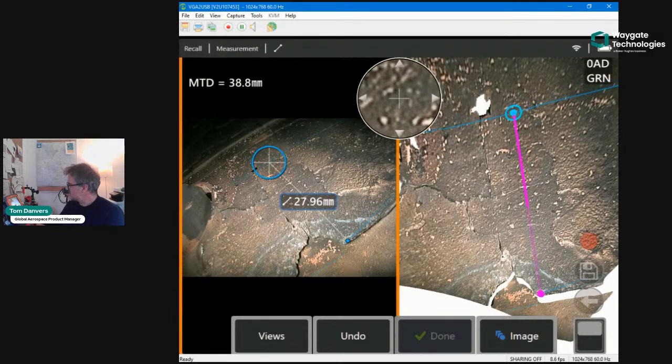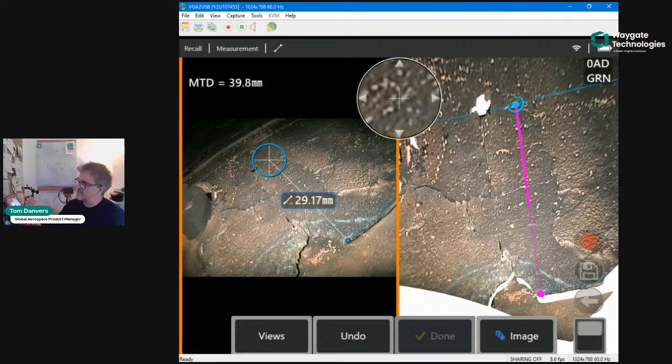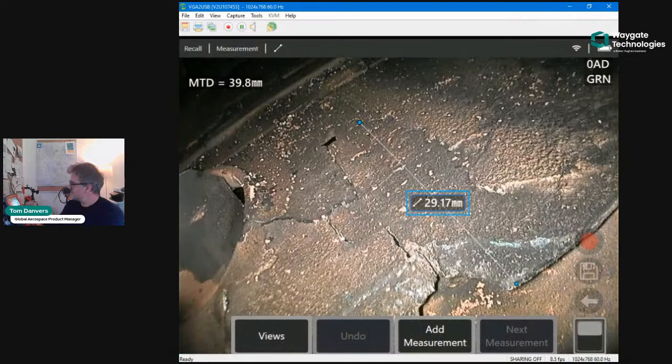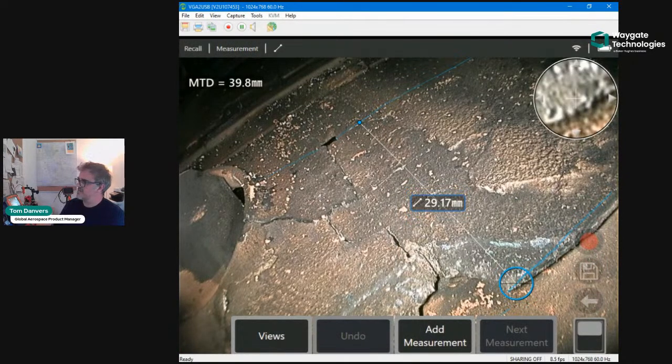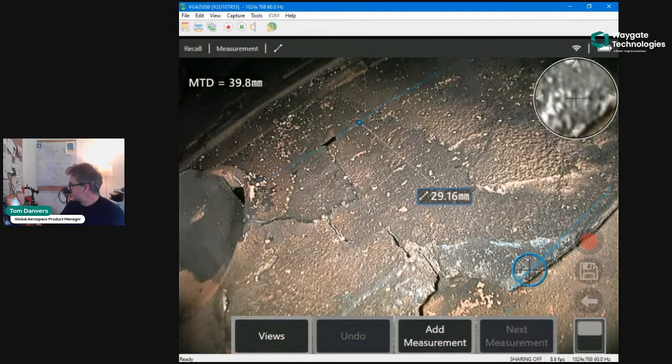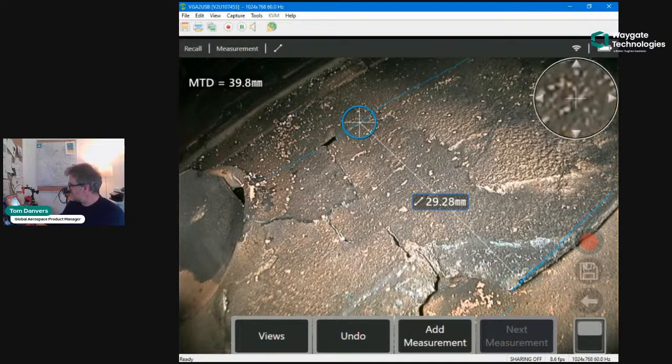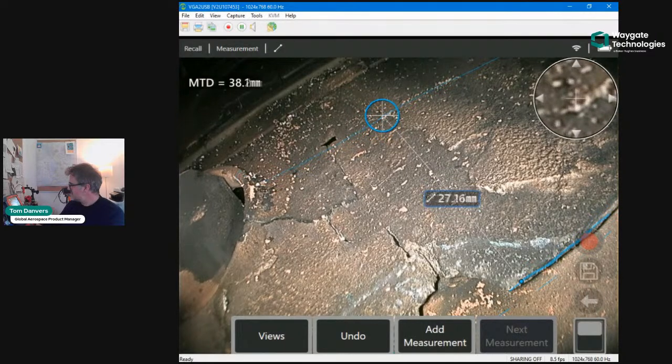So I just perhaps want to measure the axial length of this crack, even though it's kind of unzipping in different directions. If I enter that and go into my two-dimensional view, just to show it in full view and activate a cursor, you can see these blue lines, these blue surface masks. So if I chose to do a length measurement along here, it's important that I don't create a diagonal and a longer image than is otherwise necessary. So really, you can tell that this is best suited to a point to line.